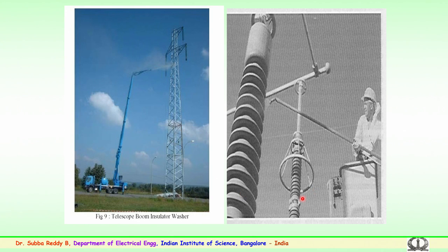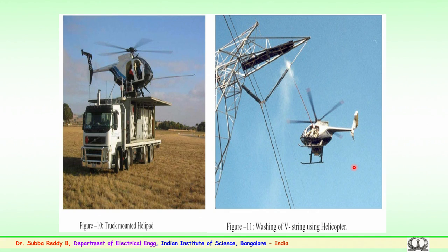So, one is live line washing, which is being shown here in this figure. Live line washing is also very important because you cannot interrupt the supply over a period of time. So, the activity of line washing has to be carried out, which is one of the methods to see that flashover of the substation equipment or the switchgear does not happen during the working conditions, particularly during the monsoon conditions. And there are other methods which are being employed for areas like high altitude mountainous areas, or the areas where the vehicle, that is a truck with a jet, could not approach.